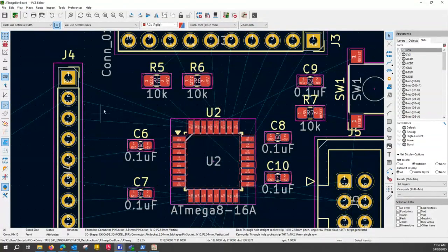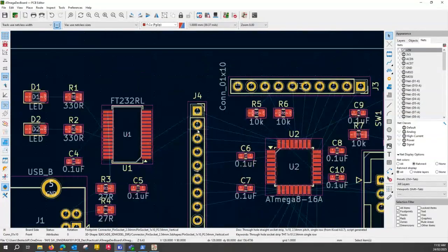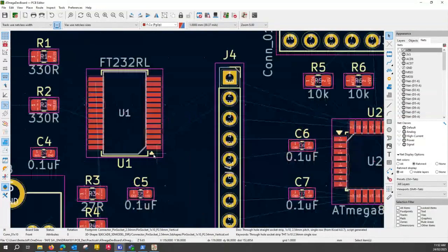So what I want ideally is, there's not much I can do on this side. So the only thing I can do is swap those two pins. And then on this side, we've got a little bit more room to move because we can either come off this pin this way or come off this pin on the inside of the chip. If we come to the inside of the chip, we're automatically swapping the position of those lines. So I'll fix this first.